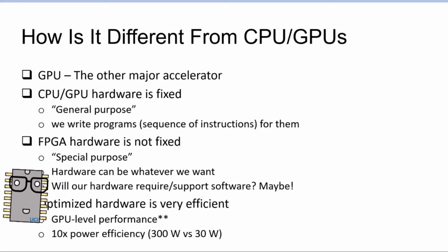But depending on dynamic profiling that you do on the program that this processor is running, dynamically you can discover something like, oh, maybe this program will really benefit from this kind of an operation fusion. And merging 2 instructions or 4 instructions together, this program can really benefit from that.